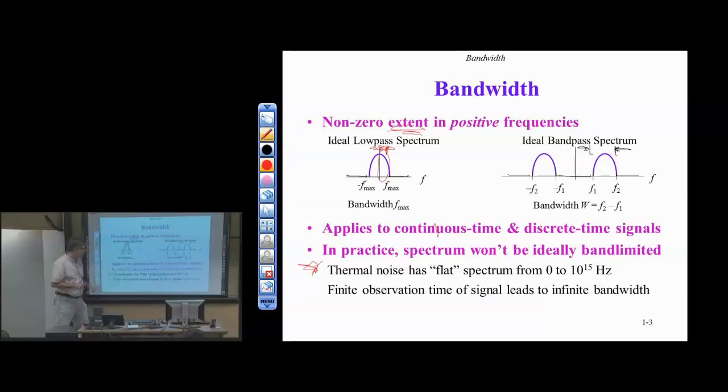Okay, so if I were to sketch this power, I have to do a power spectrum for this one, which is a magnitude squared, which we'll talk about on the next slide. This thermal noise, as a function of frequency, this would be the power spectrum, which is equivalently the magnitude squared. So this would look like this. I've got noise present equally at all frequencies. Again, it's an idealism. The real story is that there'll be a little bit of wiggle here and there in practice. The theory says it's a flat power spectrum.